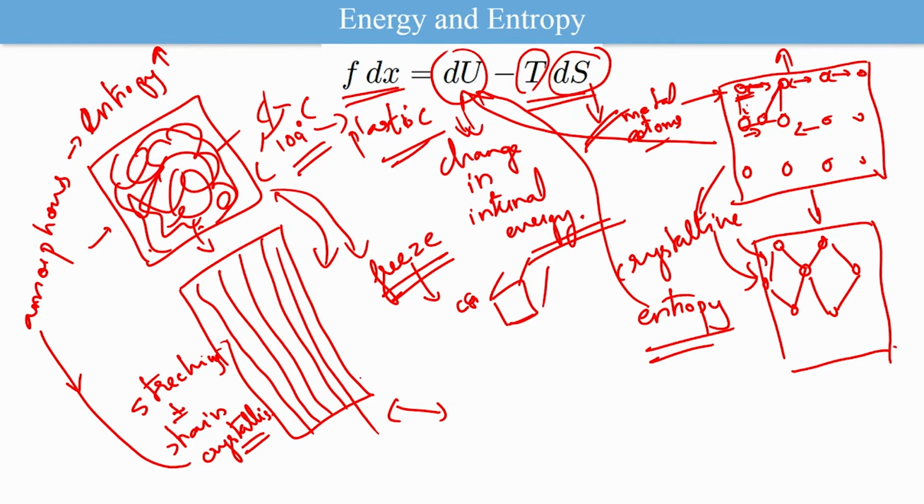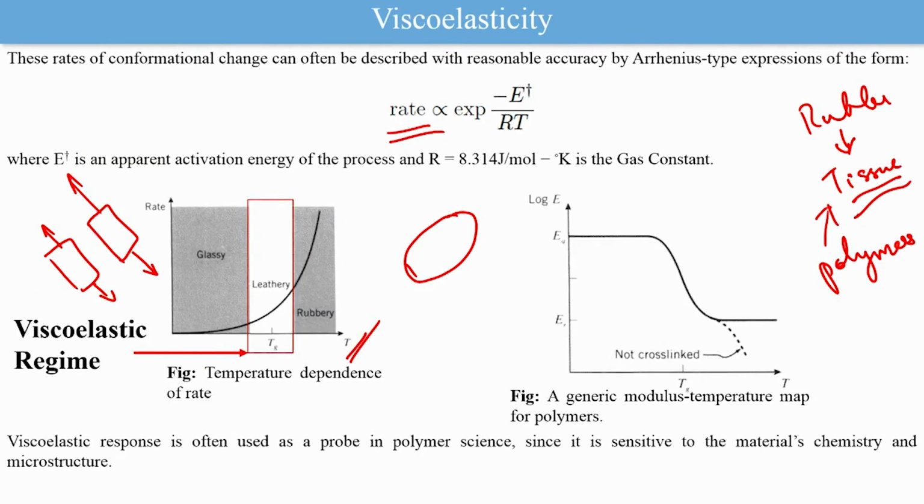And in another rubber band, you stretch it using something and again freeze it, and when you break it, you will see a very aligned structure. Okay. So, this basically shows the orientation change or the uncoiling of rubber or these kind of materials. Now, talking about this, the temperature actually plays a significant role in the mechanical behavior of polymers like rubber as well as even for tissues.